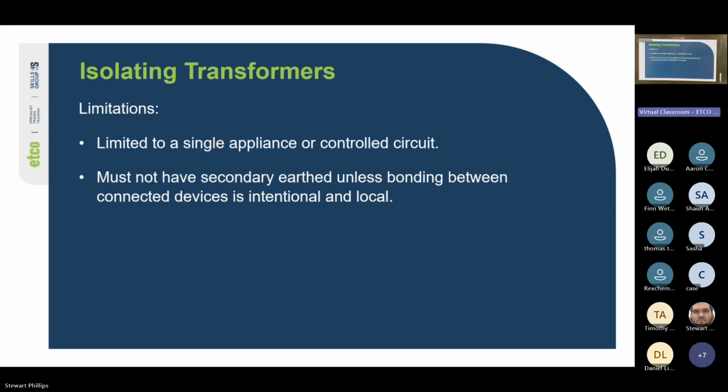Yeah, so basically, if we have two appliances and for some reason we have two devices plugged in and they both get phase to frame faults, there is a potential for current to flow between us through the earth to the other appliance, unless we bond them. If we bond them together, then it will create a dead short and blow the fuse protection on the transformer. Yeah. If we're going to use multiple appliances together, we need to bond them together.